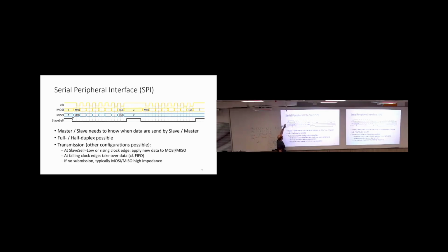If I want to send, I first have to trigger the select signal for a specific slave. Then after this, I have to put the master out, slave in signal if I want to send something from master to slave, and the slave has to post master in, slave out data if something should be sent from slave to master.